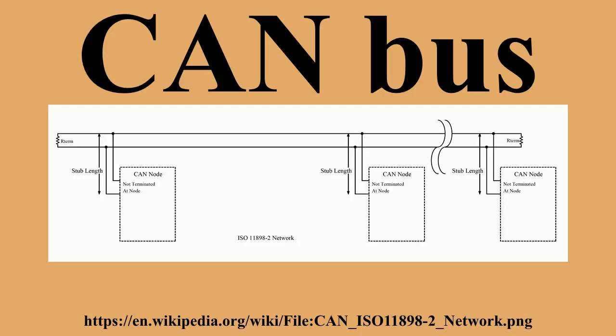In 2012, Bosch released CAN-FD 1.0, a CAN with flexible data rate. This specification uses a different frame format that allows a different data length, as well as optionally switching to a faster bitrate after the arbitration is decided. CAN-FD is compatible with existing CAN 2.0 networks, and new CAN-FD devices can coexist on the same network with existing CAN devices.